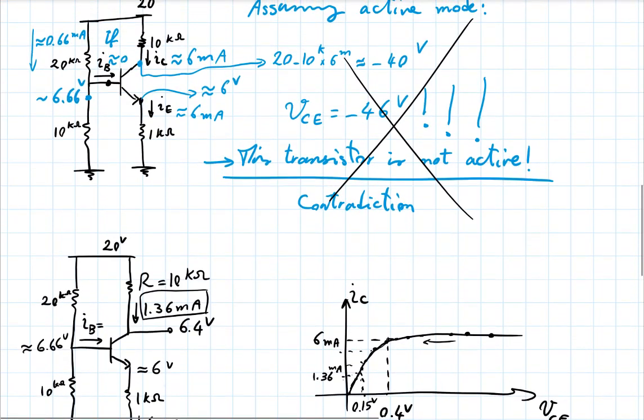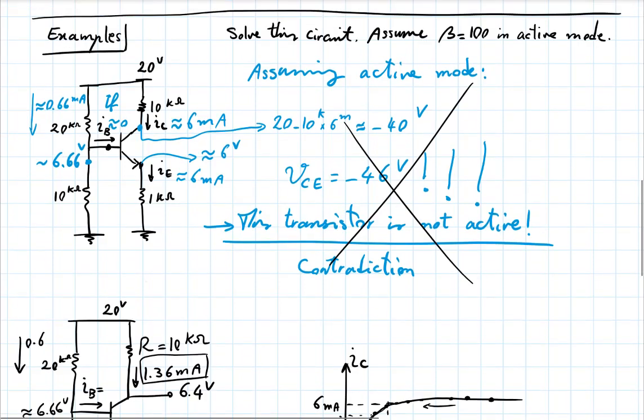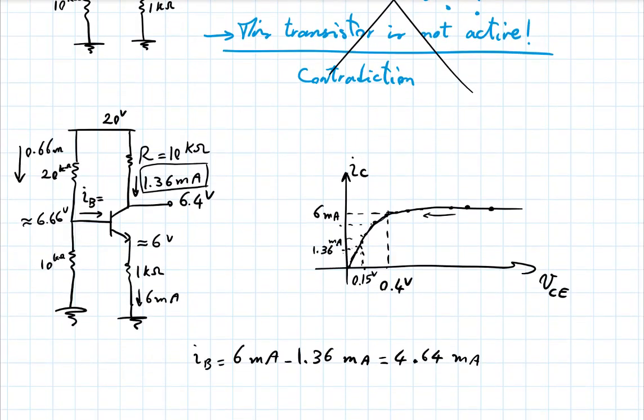What was the current we had said approximately I had here? Was it 66 milliamps? And my base current now is hardly negligible compared to that. It's almost 8 times that. So what do I do now? Well, first of all, what happened? This is clearly not beta times smaller than the collector or emitter current. What happened?